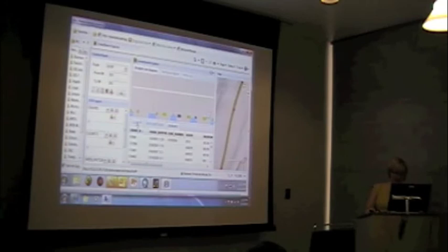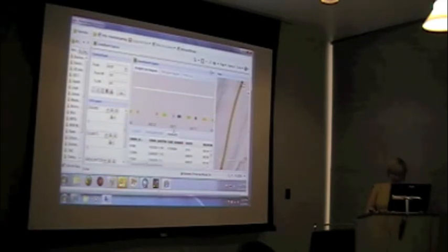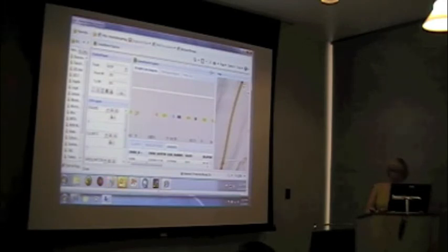So the first thing I want to analyze would be the crashes. The points here, green, yellow, these are locations of different accidents over a long period of time. As you go along the road, it will tell you where accidents happened. There is a legend for the severity: green are minor crashes and purple are severe crashes.